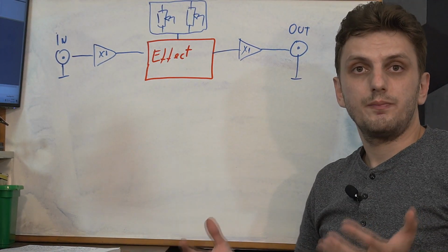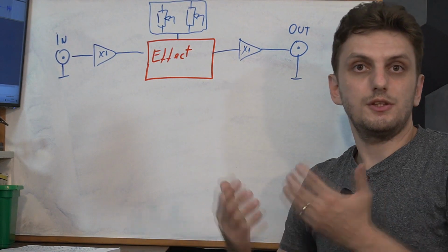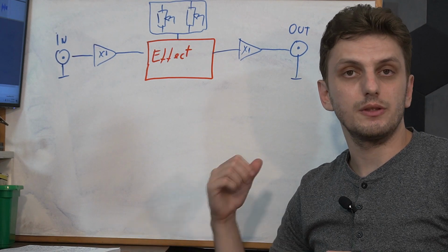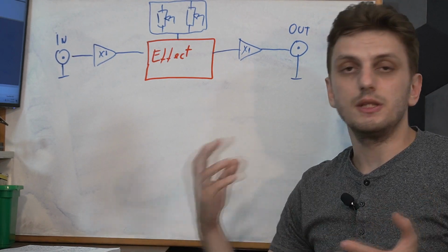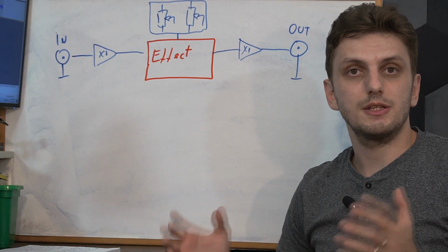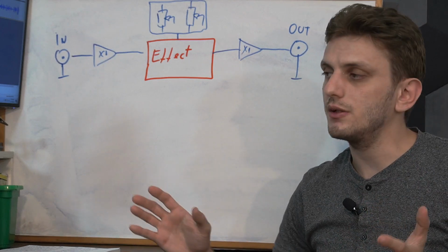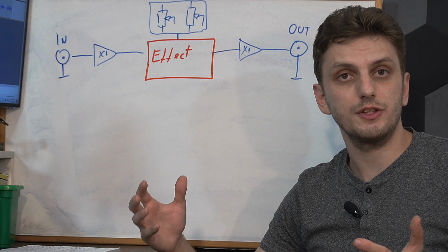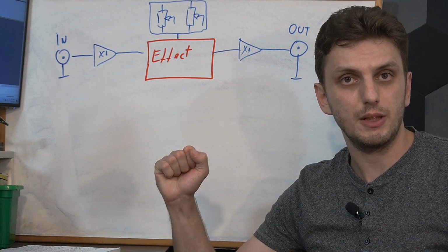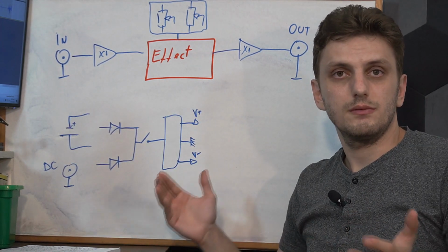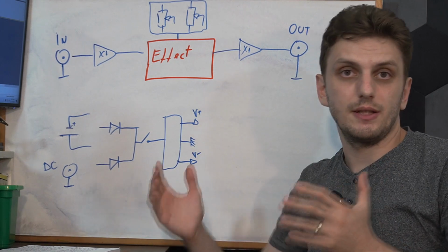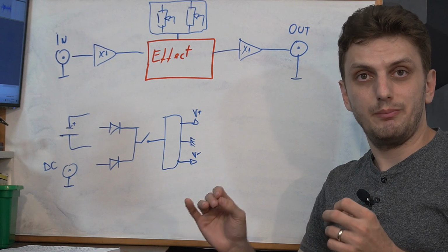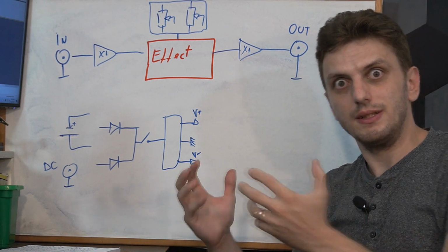And now, of course, any circuit needs to be supplied. So you'll need either a battery or a DC adapter, you'll need some sort of reverse voltage protection, some sort of filtering, power conditioning. Maybe you have a half voltage point, so some sort of voltage reference towards which you have a positive and a negative supply. Of course, you'll need some sort of switch to be able to activate and deactivate your circuit. And finally, since we're talking about effect pedals, you need the pedal itself.